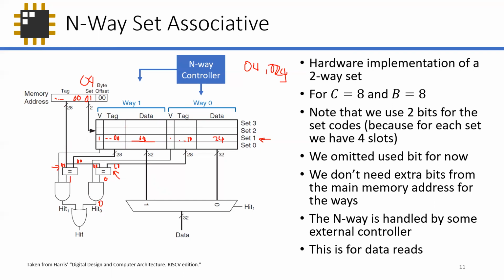Assuming the valid bits were originally 1, sorry, I forgot to put that, because this is 1 and 1, you're going to have a 1 over here. And automatically it will indicate that I have a hit. That hit goes to the cache controller, not the CPU, and it understands that you have a hit. We won't do any memory accesses. Because this hit 1 is pointing to the selection in this mux over here, if hit 1 is a 1, it will automatically select this path and load that 0, 4 data.